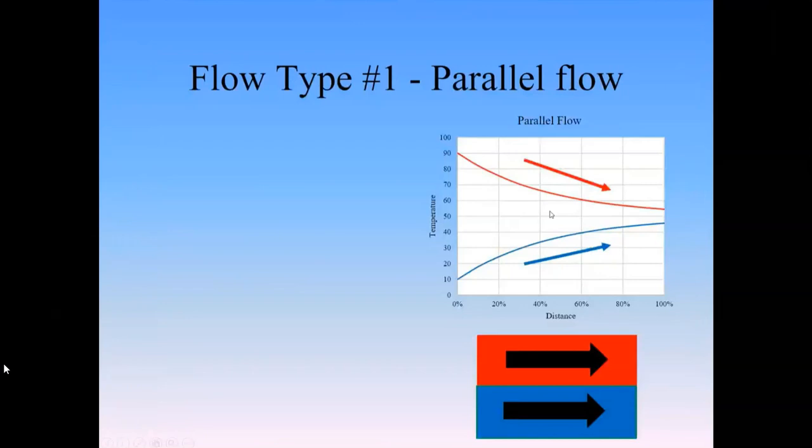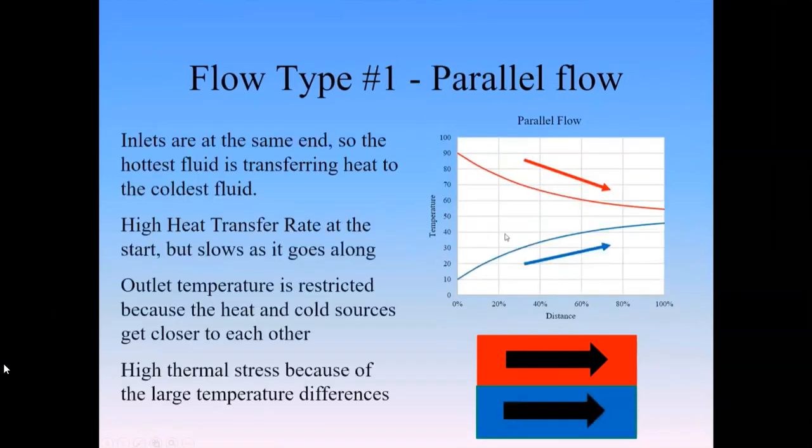The other thing that's important about parallel versus counterflow is how these things actually interact with each other, and the stresses on them, because this one has sudden changes in temperature. My temperature is changing very quickly as it moves through and then evens out.